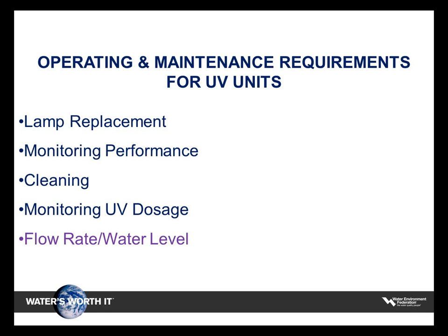Monitoring the UV dosage: we want to make sure that each system is up and running, and that the dosage is high enough to do the job, to disinfect the water. So that has to be constantly monitored as well.